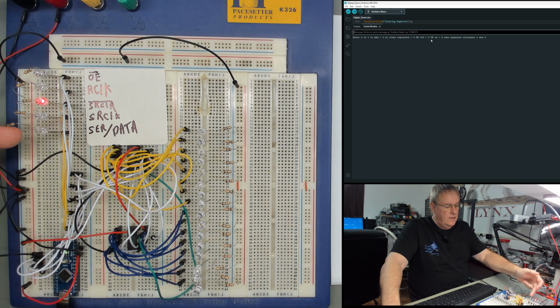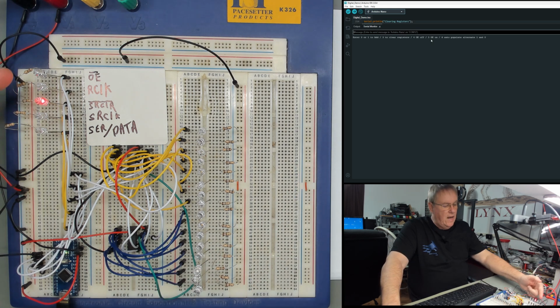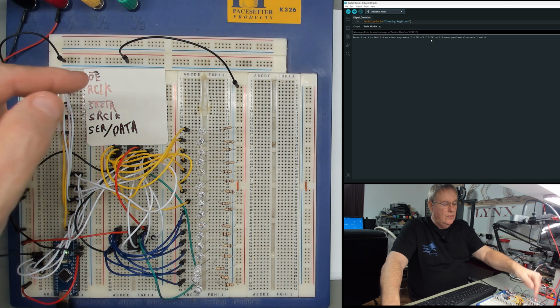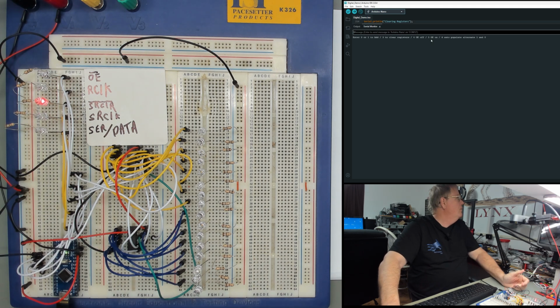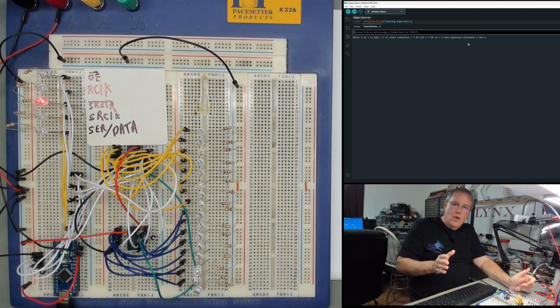Currently, if you look at these LEDs, remember, they show us the status of the data lines. Notice that the OE is low, the light's off, so the output enable is already on. And then 6 is auto-populate alternating 1s and 0s. Instead of me manually putting in one bit at a time, it puts a 1, a 0, 1, 0, 1, 0 until it fills up all 16 registers. It starts out slow and it speeds up.